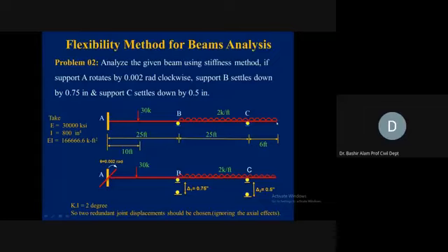With hand calculations, it may take maybe 3-4 hours to solve this problem. So now we need to act smartly. Axial information is again not given, so we will ignore the axial effects. Ignoring axial effects means 3 members we need to take out. If we take those out, it still becomes a 4 degree indeterminate problem.